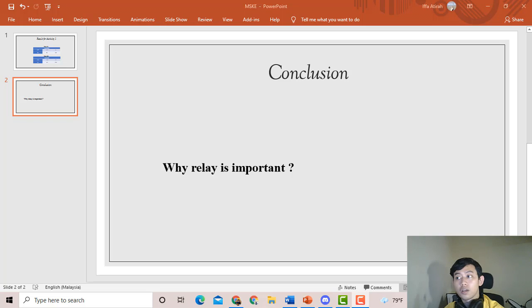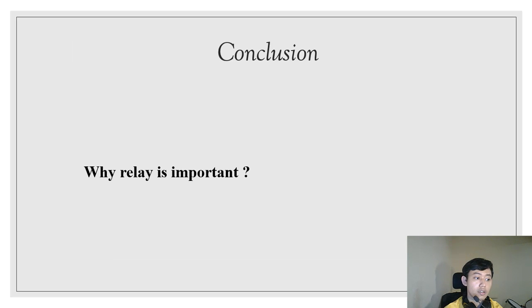As a conclusion, DTR and ITR consist of relay, and we know that relay is commonly used as a protection or switching device that can operate both mechanically and electrically. And relay has a set of contacts, which can be normally closed or normally open, and some would call it a break contact or make contact, right? So it functions to change state from normally closed to normally open, and it has a C common in the middle, right? In addition, relay can operate in both AC or DC conditions, right? So it offers complete isolation between the active circuit and the load.